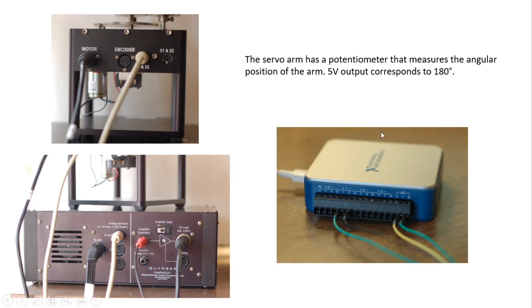And how does that work? That value is going to go to an analog output right here, and then this is going to go to the amplifier command right there. The amplifier can provide more current: the DAC cannot give you more than maybe 25 milliamp, but the amplifier can go to the load, which is the motor, and it can send as much as 4 amp, and this is going to go out to the motor right there.